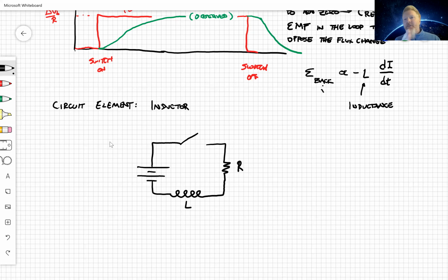resistanceless wires, there's obviously no such thing. But what you can do is take a small resistor and put that into the circuit. This resistor R here is for all the resistance of all the wires, and then you can make all the wires resistanceless. So you can model wires with no resistance by just adding a little resistor into the circuit. Part of R is the resistance for the wires. That's the resistance of the whole circuit. Now I'm going to make this inductor the inductance for the whole circuit. So it's going to be the thing that takes care of this problem. I don't have to worry about it.